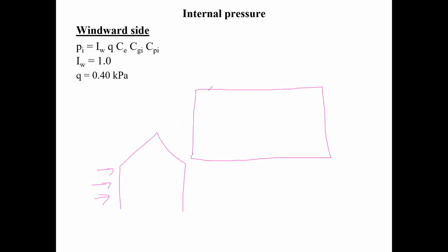The stud in my wall is not a primary structure. It's a secondary structure. You understand? It's just one member in an overall system. So the primary structure means that I'm looking at the structure as a whole, and the wind is acting on the building as a whole, not just on one little member here. Do you understand what I mean by primary structure now?